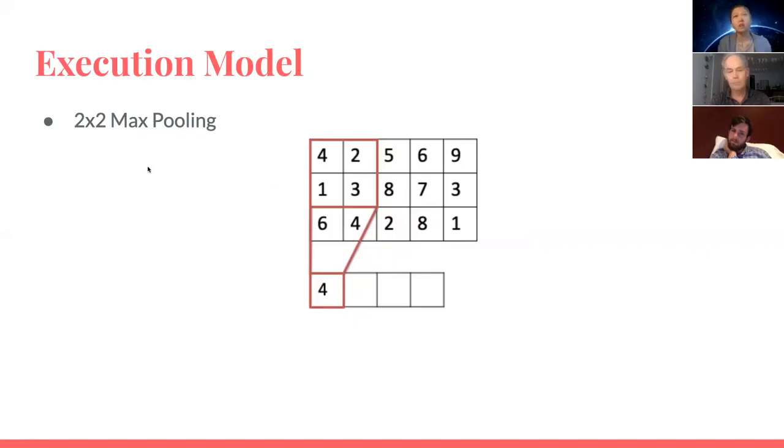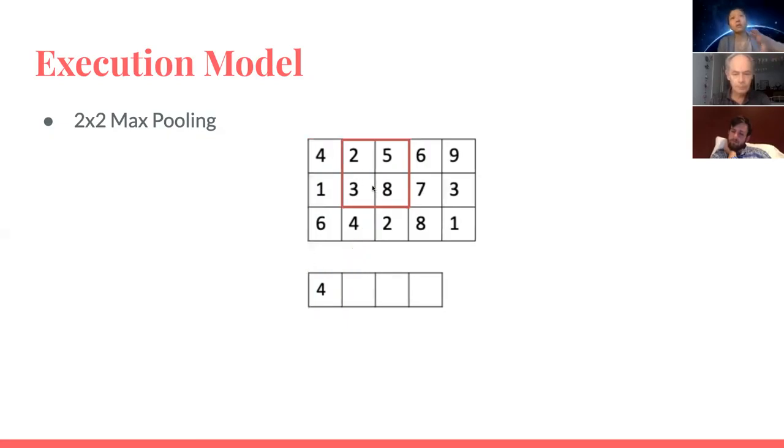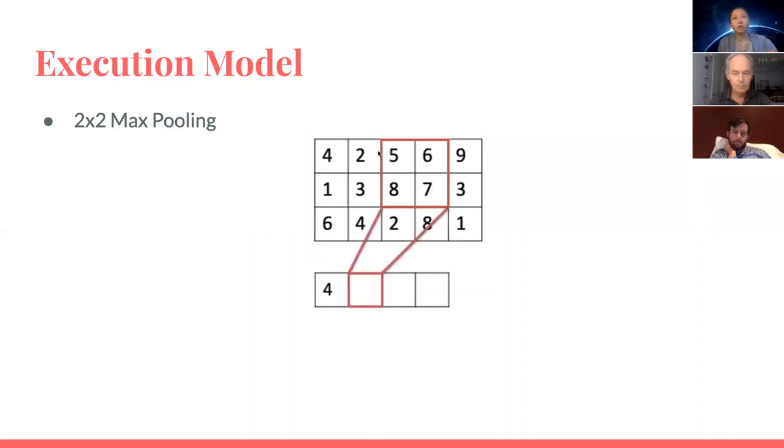Here is actually one good example of a line buffer, but this is only for pooling, instead of the input computation. For the pooling with a filter size of 2x2, here we can store the values of 1, 4, 2, 3. Actually, we don't have to store 1, 4, but once we store 2, 3, it can be reused by the next pooling operations in this line. So 2, 3 will be reused by the next operations. And then we take the largest out of the 2, 3, 2, 5, 3, 8.